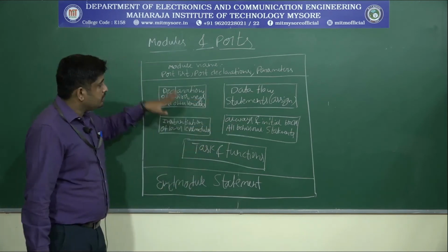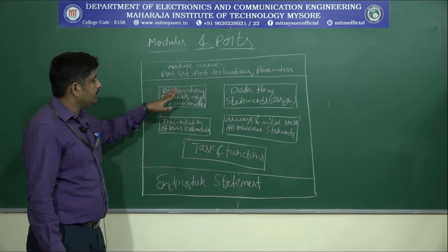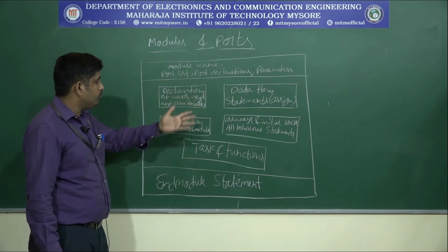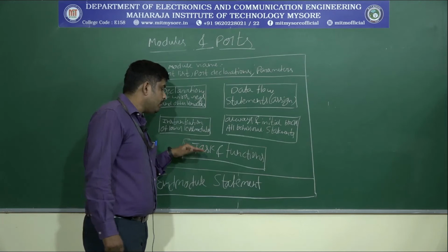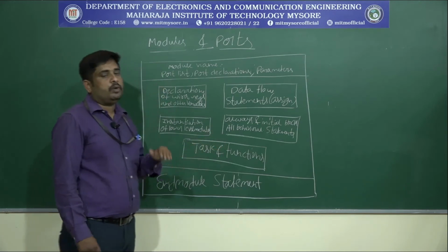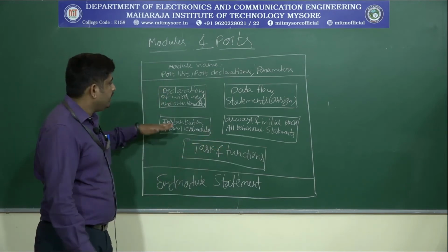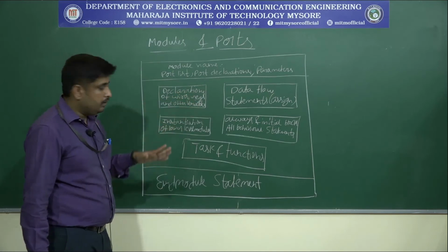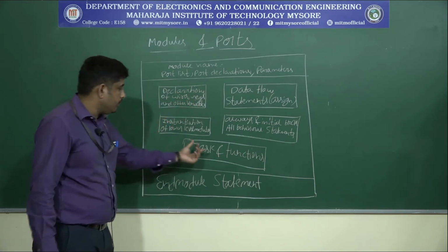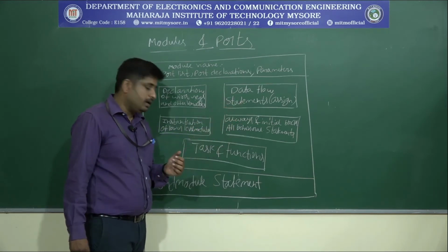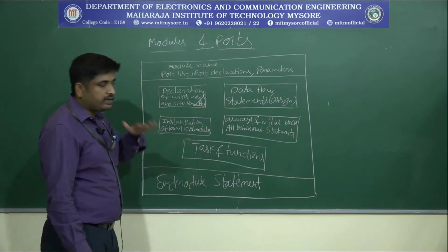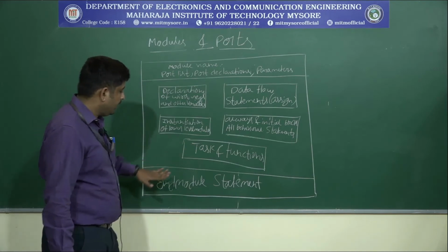After this, the declaration of registers and wires, whether it is data flow, gate level, or behavioral description. Next you have to mention tasks and functions. So what are the tasks required for data flow, behavioral and gate level description? Here we have to mention them, after mentioning the different types of description. Once the tasks and functions are completed, next is end module.